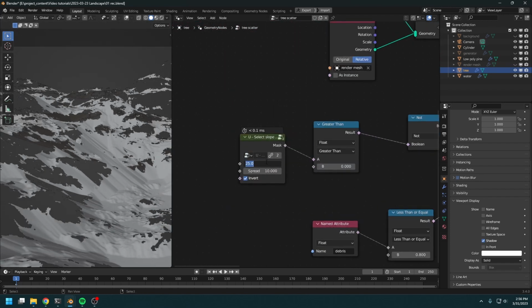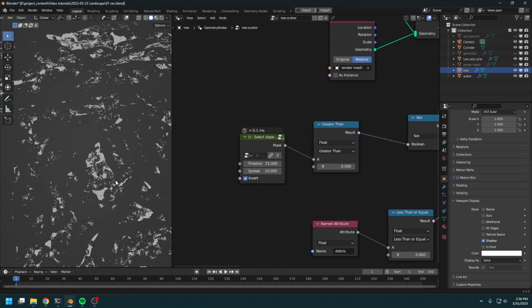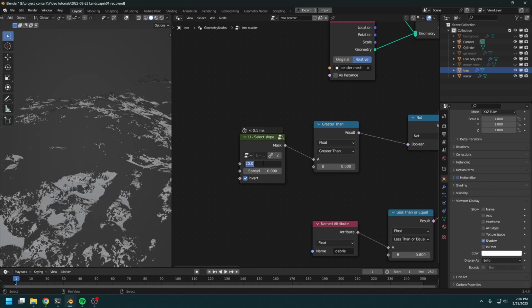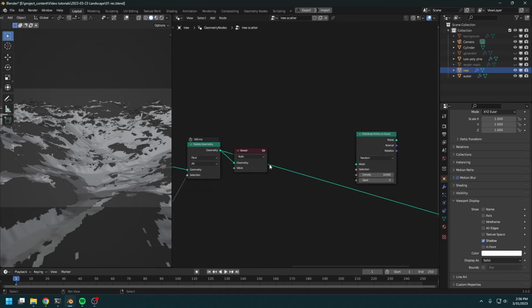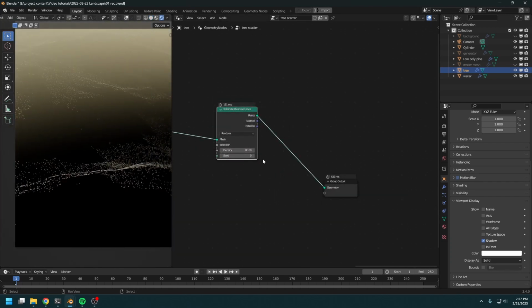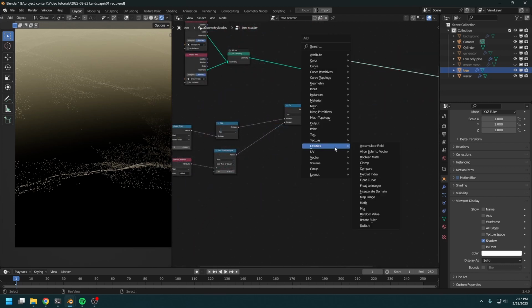Alright, we can set this to, let's say, 15 degrees to delete a lot more geometries. Let's say 20, 25. It's about time we add the points on this surface. Let's just set the density to something lower and let's see. I think 0.1 is still a little too much, but anyway, let me just use the slope angle to control the density as well.